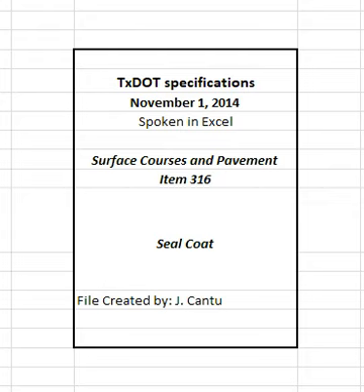3.1.1 Transverse variable rate. When a transverse variable rate is shown on the plans, ensure that the nozzles outside the wheel paths will output a predetermined percentage more asphalt material by volume than the nozzles over the wheel paths. Use a dual spray bar distributor as desired to provide for a transverse variable rate. 3.1.2 Agitation for asphalt rubber. If using asphalt rubber, furnish a distributor capable of keeping the rubber in uniform suspension and adequately mixing the asphalt, rubber, and any additional additives.